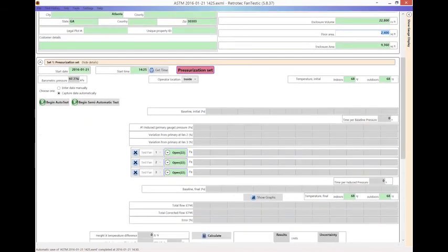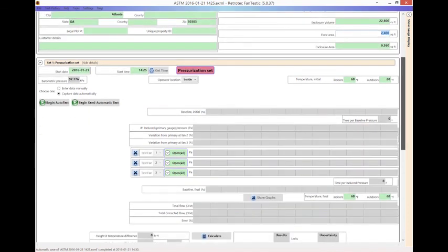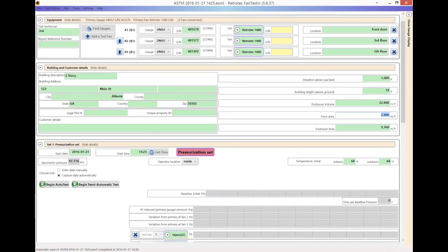Okay, so Joe, yes, sure. It should be mentioned here that if you are doing a test, let's say like air changes, and you want air changes at 50 pascals or something like that, that requires volume. If you enter the volume, it will give you air changes. You don't necessarily have to put in the surface area of the building to run the test. If you do put in the surface area, it will give you results that are based on surface area.